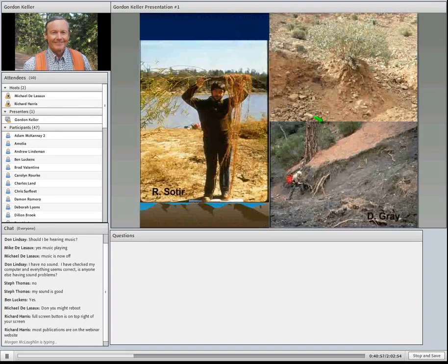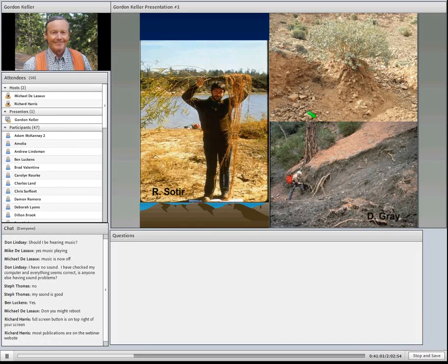These are from a variety of different areas. The advantage of vegetation is just these roots. They help anchor the soil. This is a willow, a salix family, what we use a lot here in the West for some of our stream stabilization projects and also some slope stabilization projects. This is an example of conifers that are basically buttressing the slope. These roots are anchoring the soil here, whereas next to it over here, the slope has failed. And this photo Don Gray sent me, and his book on biotechnical slope stabilization is an excellent old reference on this whole subject. And this one up here on top just shows, again, the effective roots that are holding this dry slope in place. And next to it, it's raveling. Right here, it's holding because of the roots of vegetation. So vegetation's good stuff. And inexpensive, aesthetic, environmentally friendly typically, so it's a good place to begin.